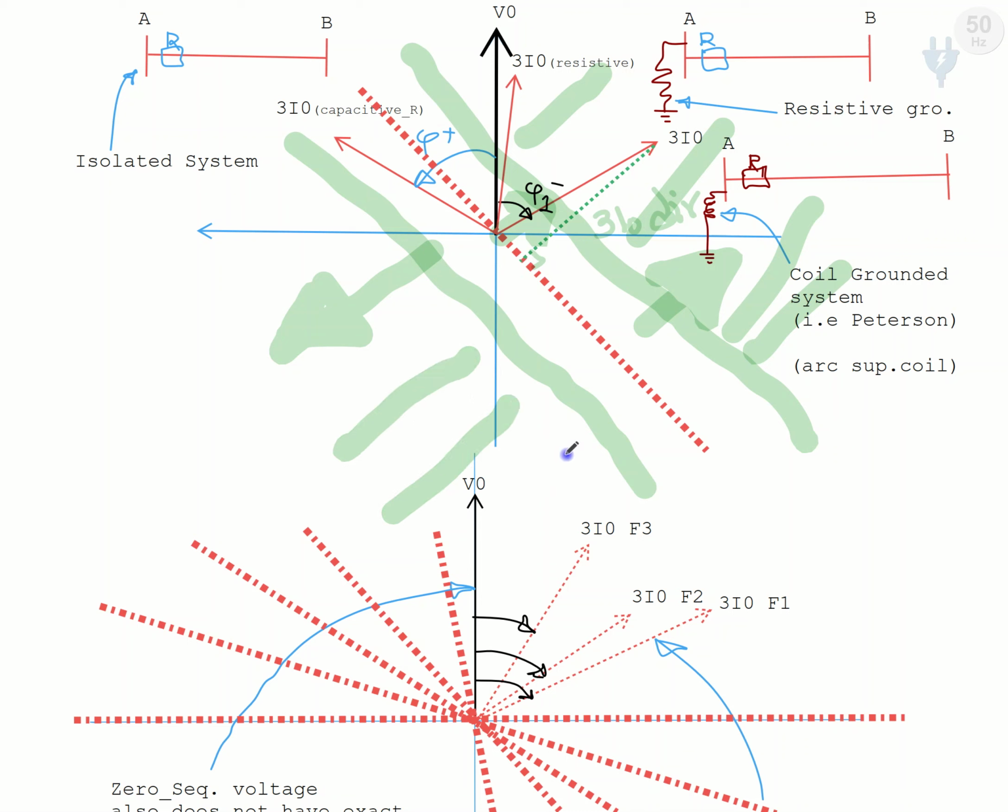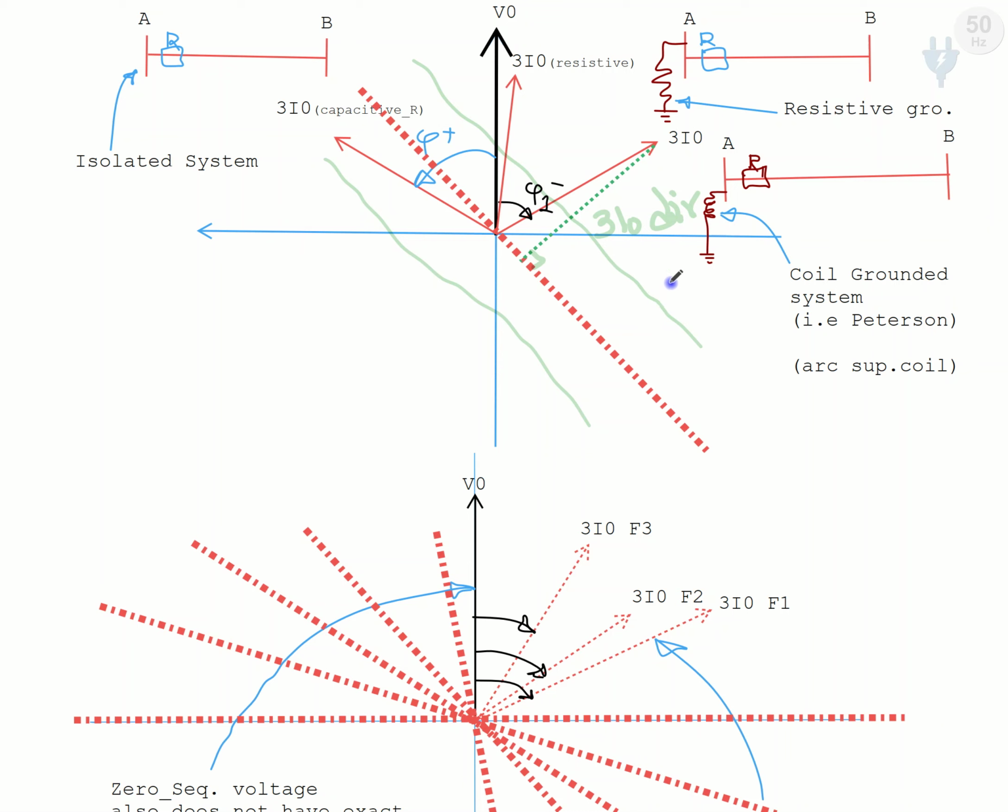And after that, whenever the zero sequence current increases beyond this value, then it will operate and it will detect for the reverse direction. These two axes are called minimum polarization axis. For more clarification, let's view an example.